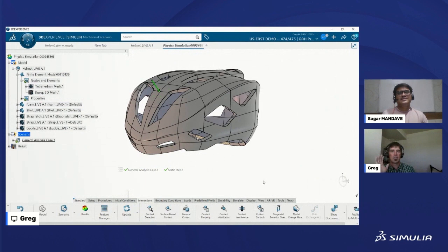What it says is, all right, when you're solving, just look at all of your surfaces, all your element locations, and software, you figure out if stuff is going to touch or not. And so it's a really, really nice way to do complex contact like this, where I have all these crazy little surfaces back here, and I don't have to deal with it.